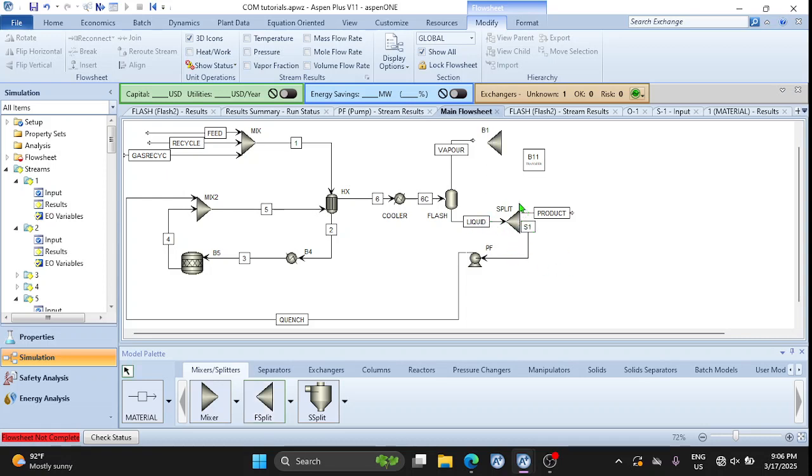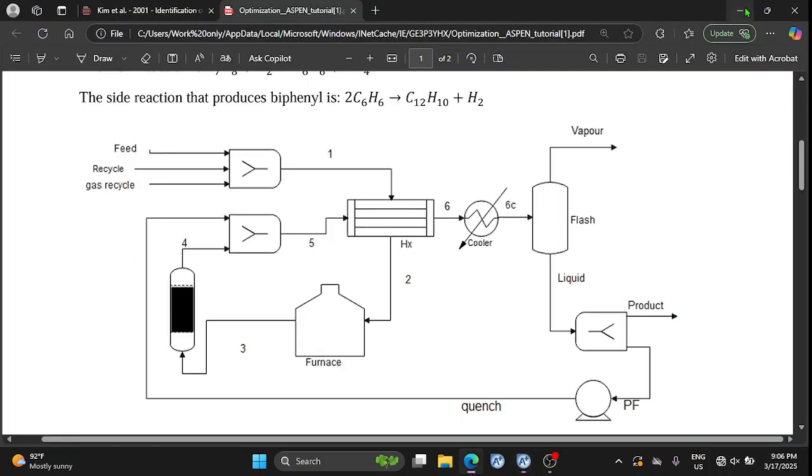So the liquid stream down here, we have a split. We are sending some back and we are removing some, right? So I have a split here. I would send some of it away and then I can recycle some of it. So now when we do this, material won't pile up in the system. So this is what we do with recycle streams in Aspen. We split it up so that material wouldn't pile up. It always has a place to come out from. So it's just something for you to take note of.